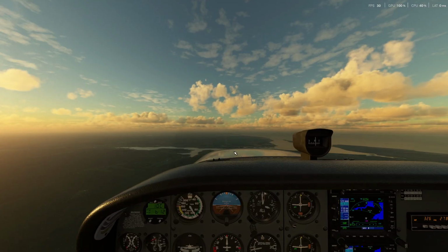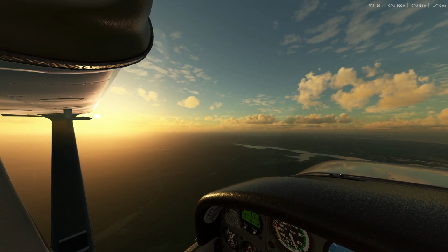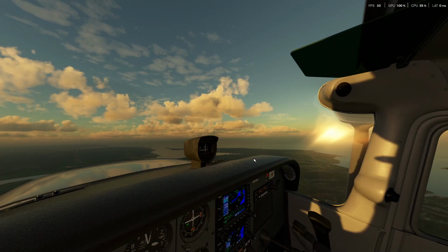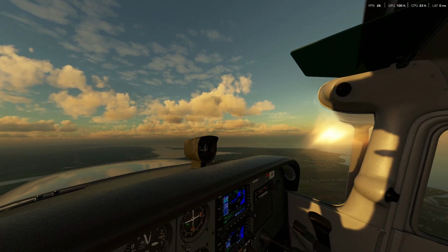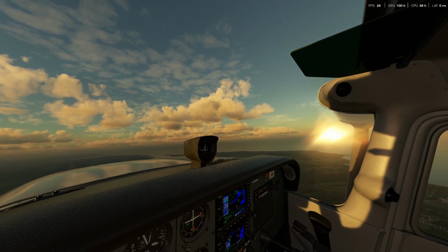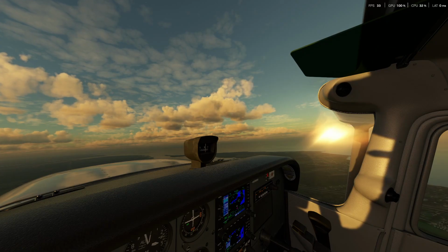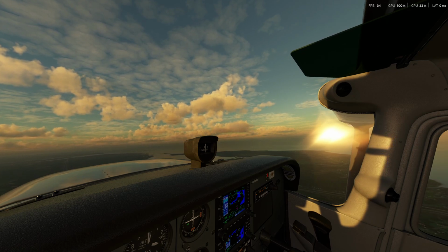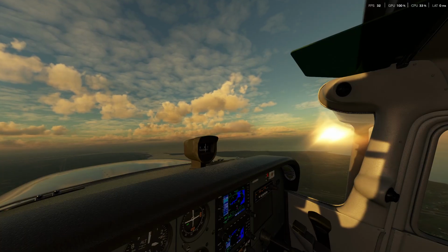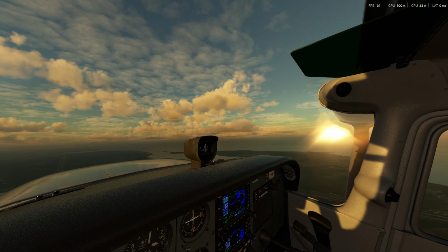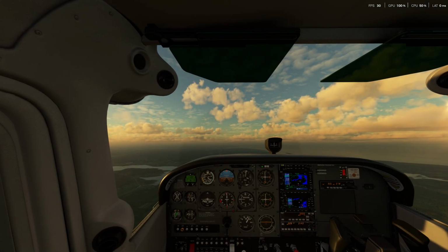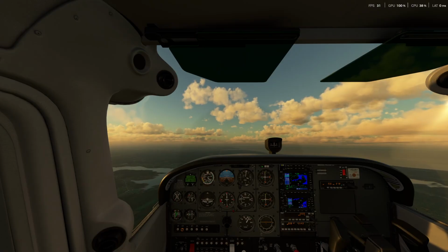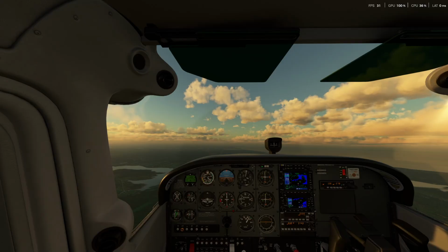It's a good habit to get into to always look outside to check. So you want to look left, you want to look right, and keep a visual outside the cockpit primarily most of the time. So we're starting to see some clouds here. You want to keep a lookout for clouds and stuff like that, but also for other air traffic, especially VFR. Not a lot of people are on frequency. The en route frequency is short, but it's a good one. Not everybody uses the radio like they should. So it's always good to keep a lookout.